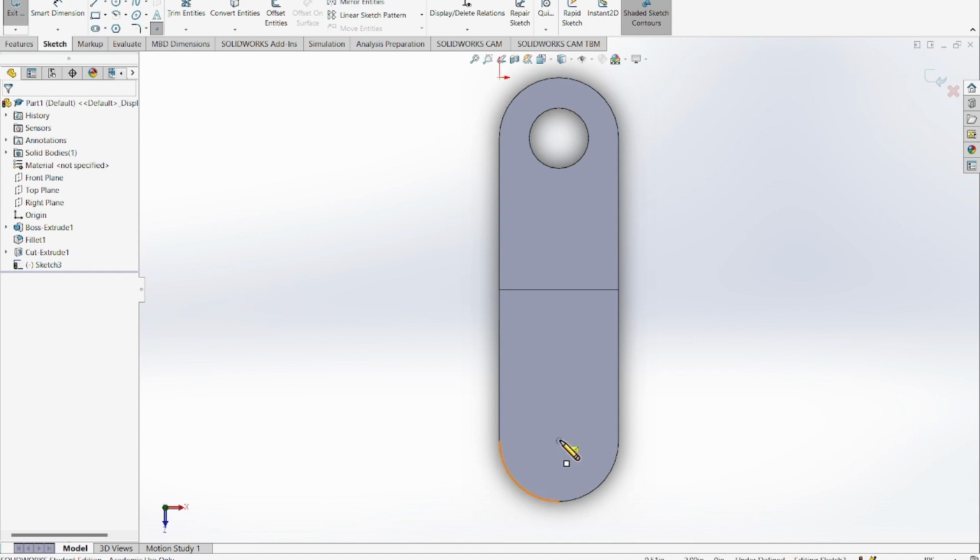Then I'm going to make it concentric in the middle. So this one right here, you can just choose the option of using a secondary hand. And the secondary hand is actually these little lines that you saw right here. If you're trying to make it center right here, if you're going for the middle of the center of the items or the selected point, it'll give you a secondary hand and it'll help you out right here.